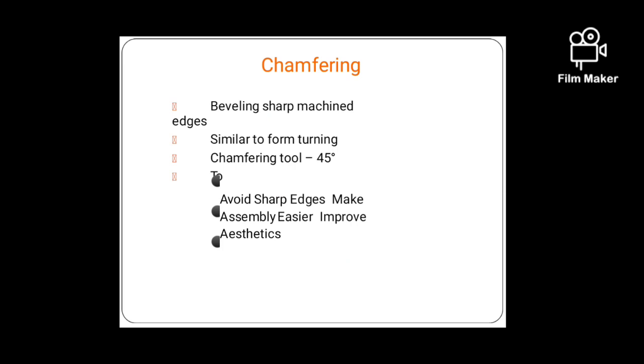It is also a process similar to turning. The chamfering tool angle is 45 degrees. It avoids sharp edges, makes assembly easier, and improves the design.